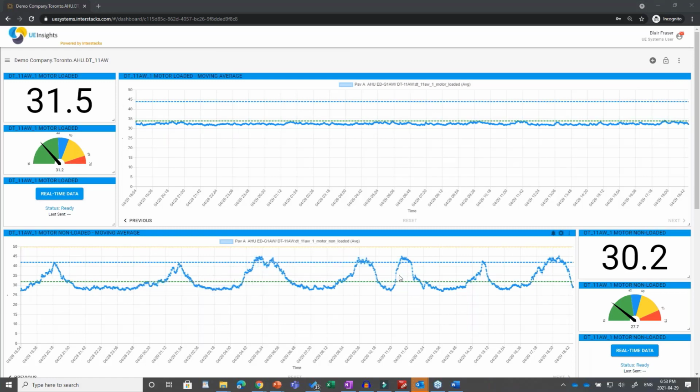And again, this is a great indication of this bearing needing lubrication or starting to fail. The only way I'm getting to know that is if I start to apply some grease to it. So how we start to differentiate: what we do with those 8, 16, and 35 decibel limits is, depending on the variation we see in friction, that's where we'll send our alerts.